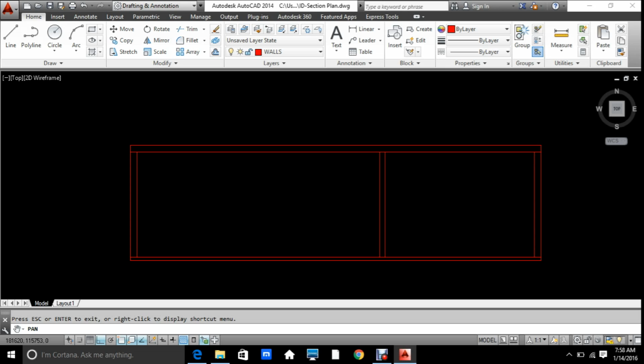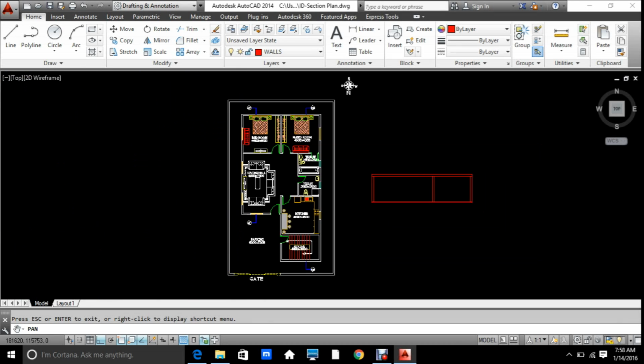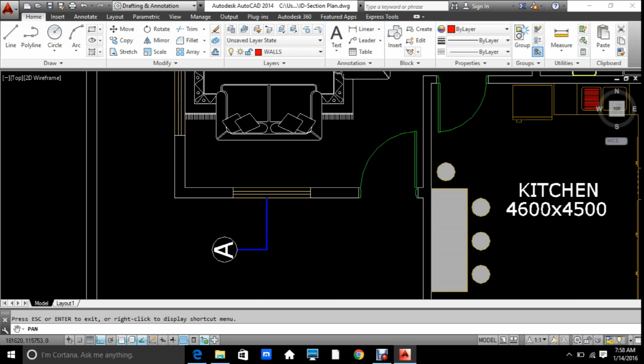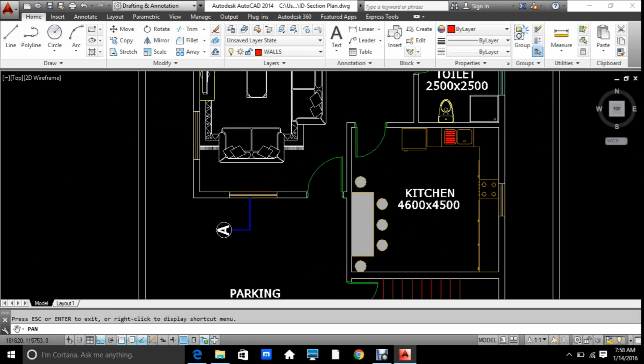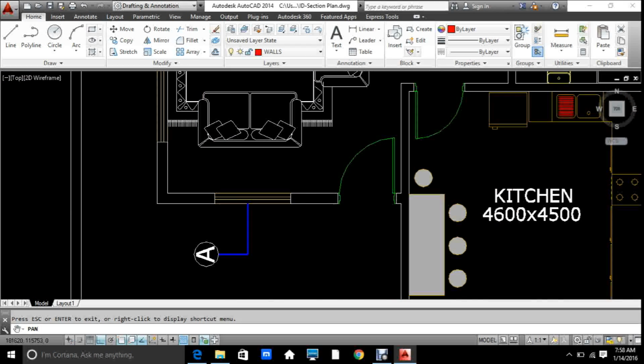Okay, now this forms a basic model of the section which is covering only the walls. Here we are just doing the walls. First we can go through the section and check how many walls we are cutting and just draw the wall. Okay, now I come back to the section again. I have to check in each wall, going one by one, whether there is any window or any door. Okay, or any ventilation.